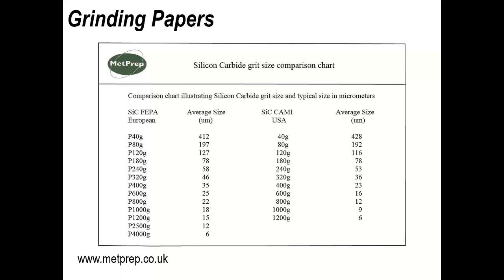And whenever you're grinding a sample, you are grinding, first of all, in one direction, and then you're rotating the sample, as you'll see me do in a moment, in the other direction. And what we're trying to do is remove the scratches we put in with the first. It sounds a bit weird to say we're taking out imperfections, but in reality, that's what we're doing. So we put scratches or grooves in the surface as we're removing material, and then we rotate the sample to improve it on the next. But obviously, you're adding scratches again on the sample.